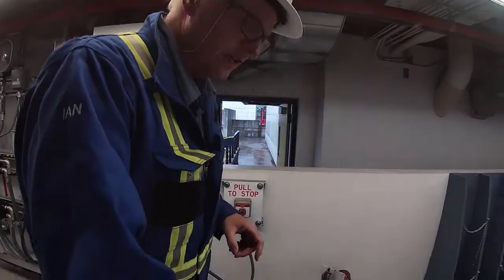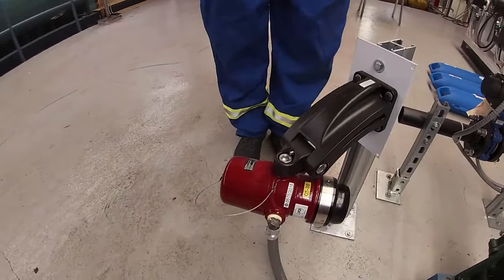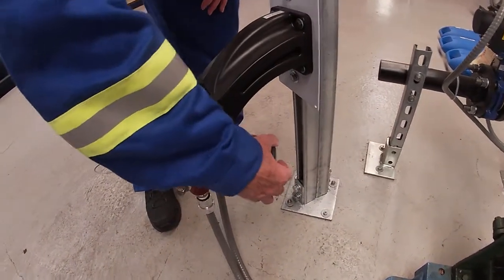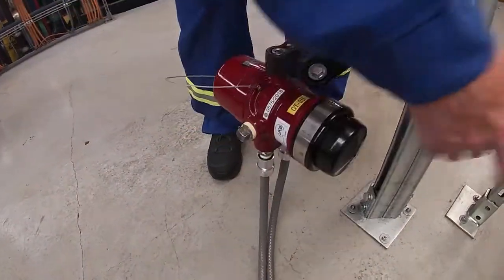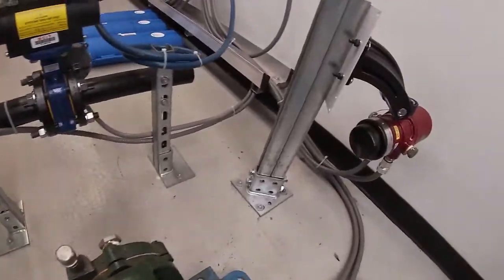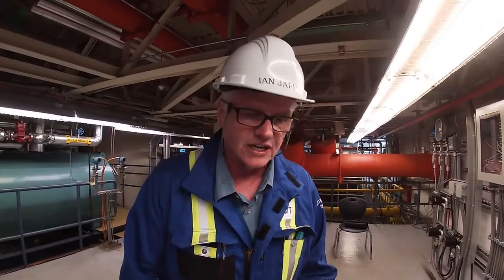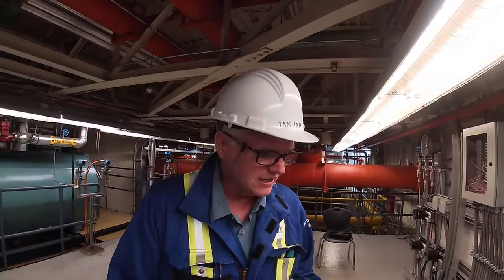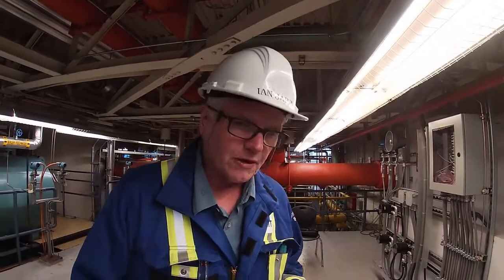The other things we have here are 2 fire eyes. These are IR detectors. Right now they have caps on them, just to keep them clean. When we're testing, if you want to test one and not the other, we just take one cap off. So what these are doing is simulating a pump that would have seals on it, and if the seals leaked, we could have an explosive atmosphere and we could get a fire. I've seen it in plants before where the seals on some pumps will leak and actually have flames coming out of the seals. If we had that sort of condition, we would want to shut equipment down.